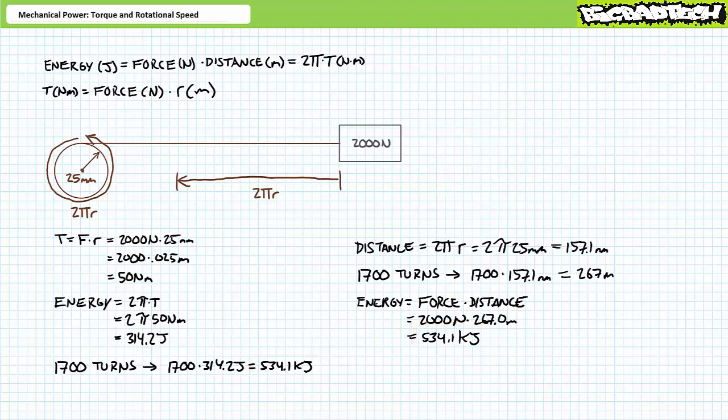And the magic show ain't over yet. Left out of this discussion entirely is time. Suppose this shaft performs these certain number of revolutions within a given time period. This means the same amount of energy can be input to our system slowly or rapidly, and this time rate of energy change can be quantified. I'm of course leading up to a discussion of power. Power is not energy. Energy is not power. Power is equal to energy over time. Power is a time rate expenditure or production of energy.